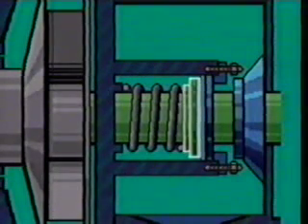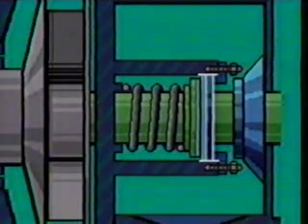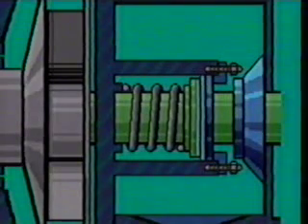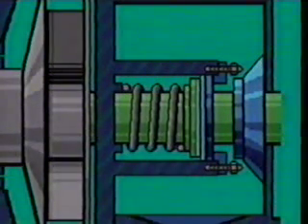There's a wide range of mechanical seals available today, but they all have similar methods of operation and similar components. Rotating parts are attached to the shaft. Stationary parts are secured to the seal plate. The seal plate is bolted directly to the casing. The highly polished sealing faces of the rotating and stationary parts are held in contact by one or more springs. In this manner, a seal is made to prevent leakage. That's the typical structure for all mechanical seals. Let's go on to bearings.